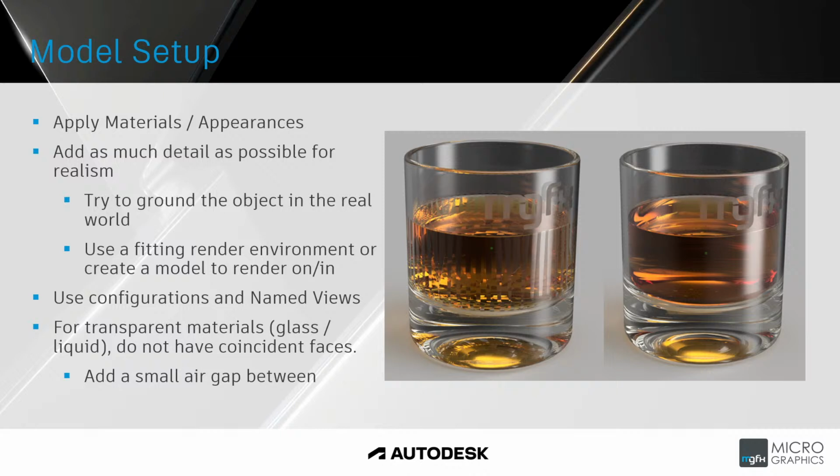And the way around this is to add a very small air gap between those objects. So if you have a window and a window frame, don't have the glass of the window right up against the window frame. You can add a small gap. In this model, I think I've got a 0.1 millimeter gap between the glass and the liquid. And you can see on the model on the right hand side, when that is rendered, we don't see that banding in the model, and it still looks as if that liquid is filling that glass completely because the gap is small enough not to see it.